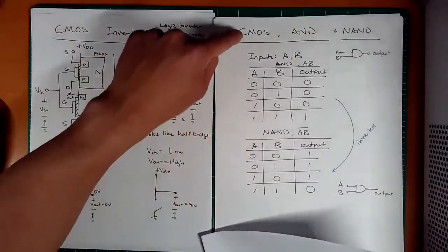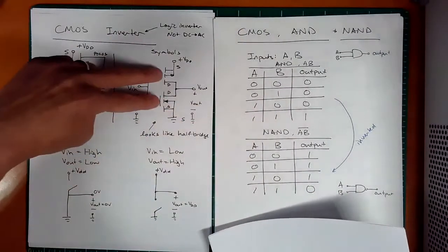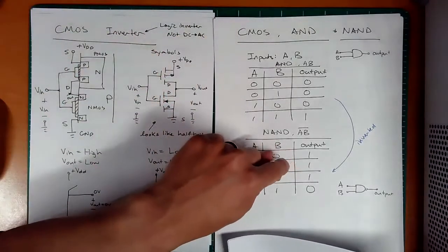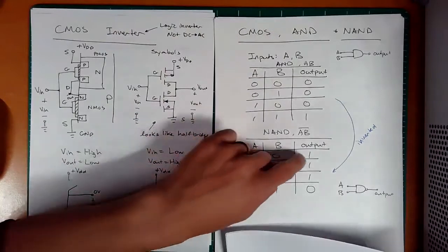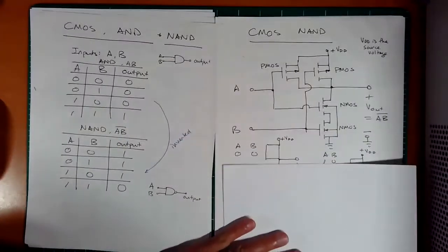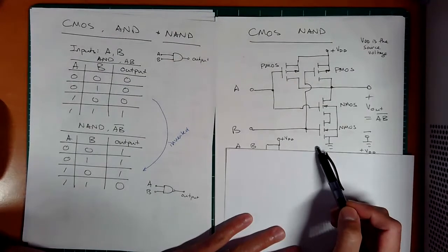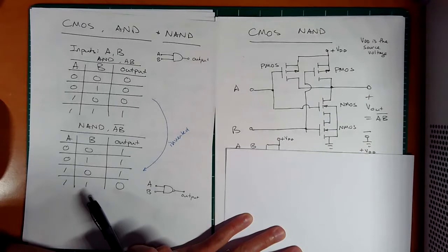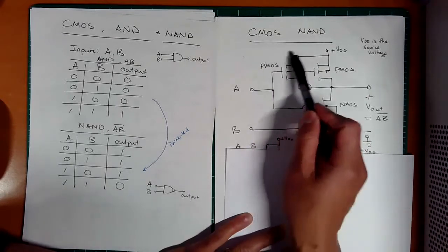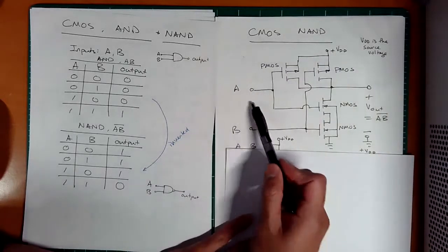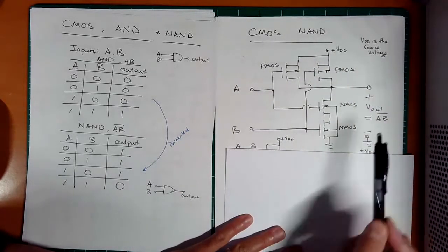So what we're saying is, let's combine NMOS and PMOS, and we call that just CMOS, in a way that we can create this truth table. So we'll have two inputs and we'll have this as our output. All right, good. Let's keep moving. And so what does that look like? It looks like this. I know it seems a lot more complicated, but notice there's 1, 2, 3, 4 MOSFETs all combined together. We call this CMOS, and this is creating a NAND gate. Notice there's 2 input voltages and 1 output voltage.